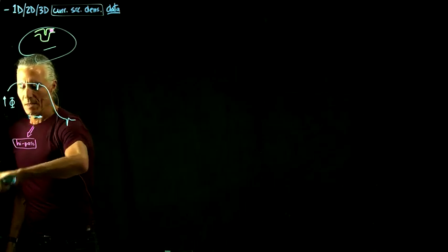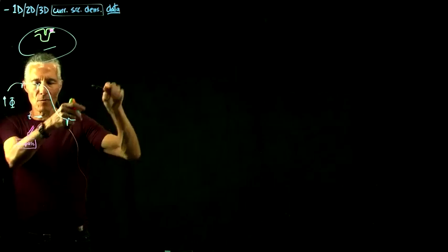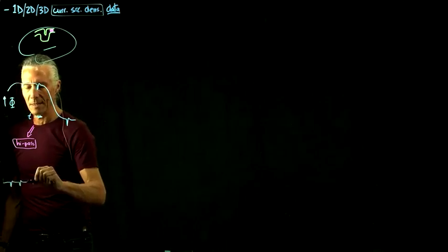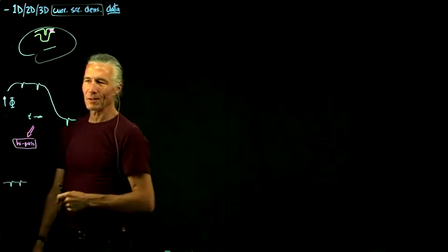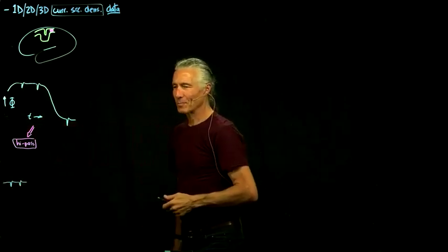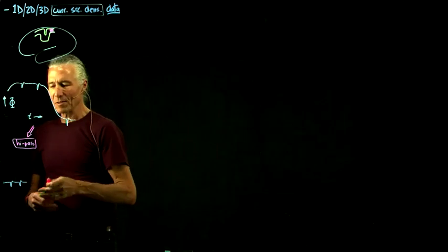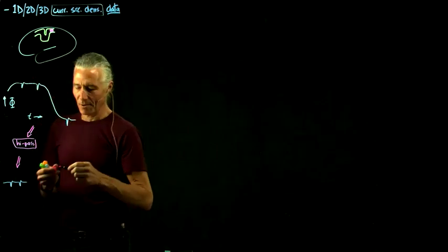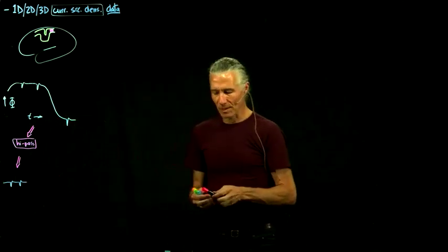So you'll filter out that low frequency change. So you'll just see the spikes. And then usually you flip them around so that they look like regular spikes. So that's if you're doing single unit recording, trying to isolate individual cells.